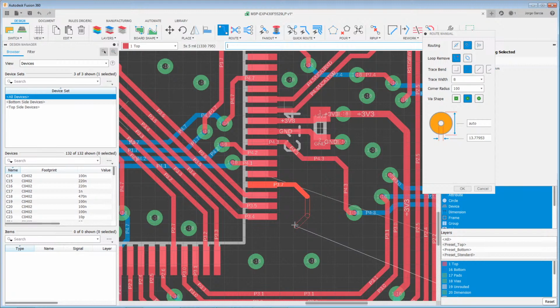It'll cut into the trace a bit more. In really thin traces, like what you may find in high density boards, over etching can be a problem and can cause a board to fail. So typically we recommend doing 45s, but if you do 90s, 90% of the time it's not going to be a problem.